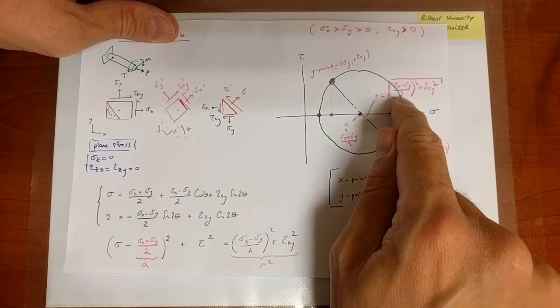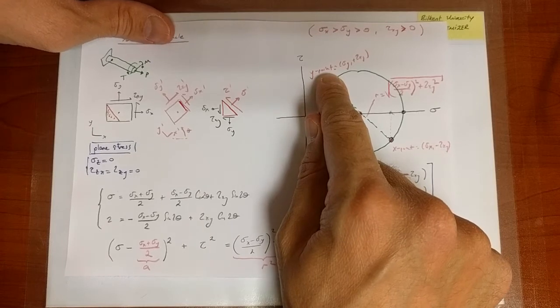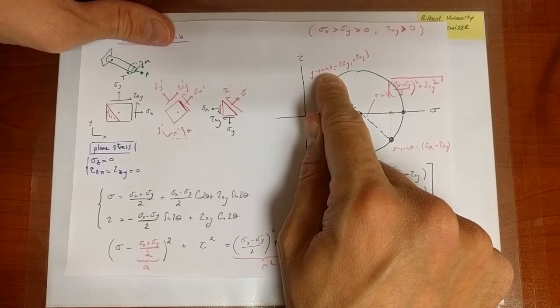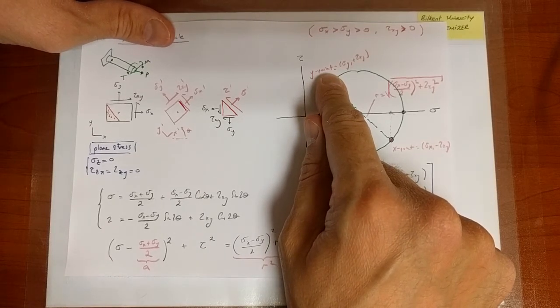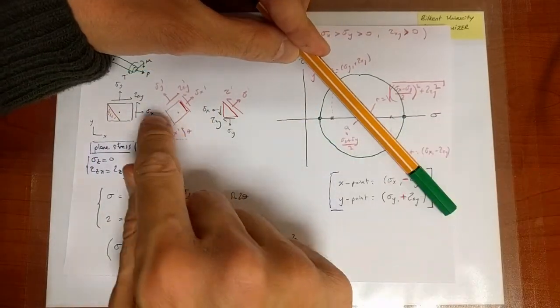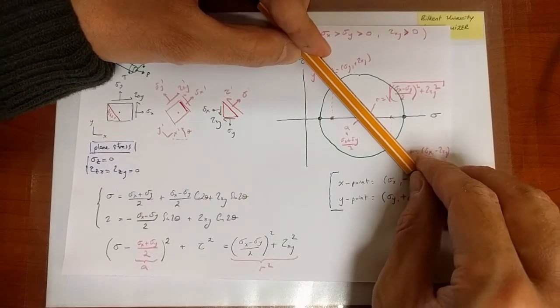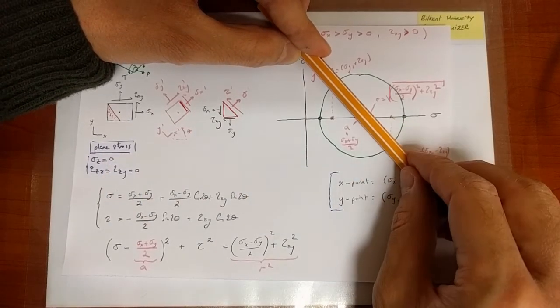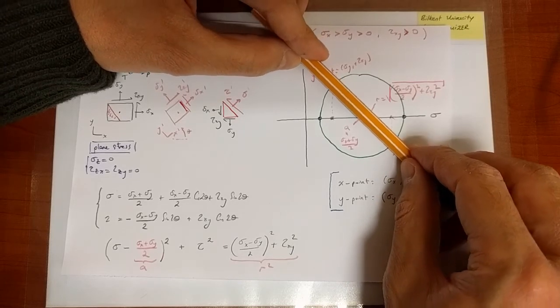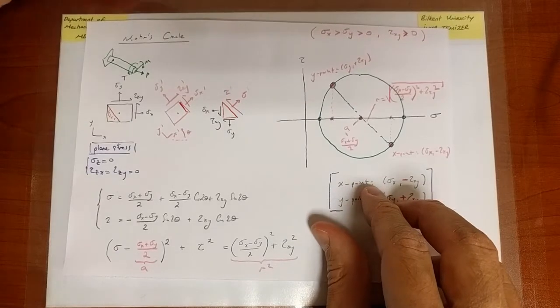Here, to go from one to the other, from x to y, it is pi or 180. Which means that if I wanted to start from the original picture and rotate by a certain amount theta towards some other picture, that amount of rotation is going to reflect twice as much onto the Mohr circle. Onto the Mohr circle, it will reflect twice as large.